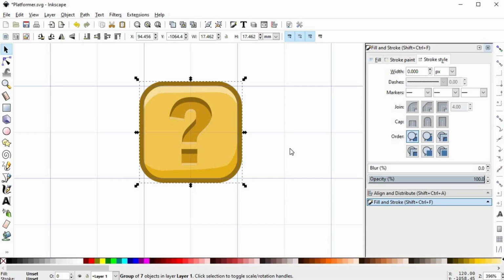But the problem is that we need to enable and disable a couple of options. Don't worry, it's not that complex. Enable snapping again. What we want is to snap the block group to a grid rectangle. But the problem is that the options by default will make it snap to a corner node.